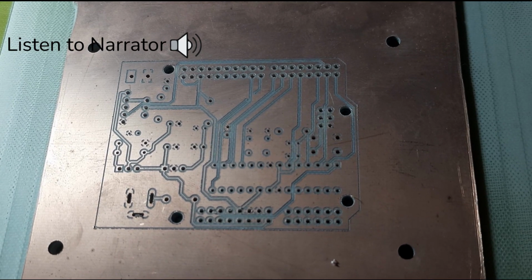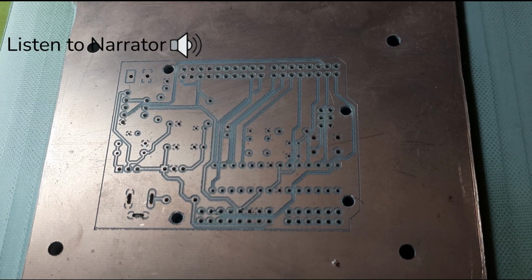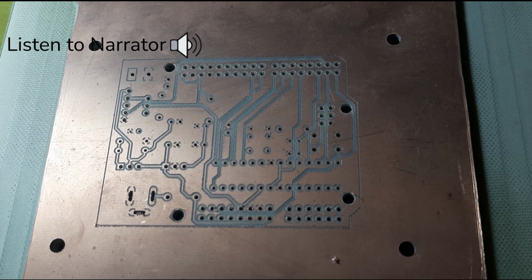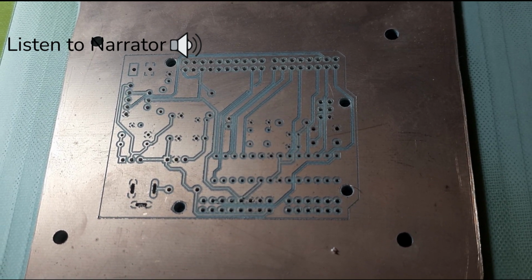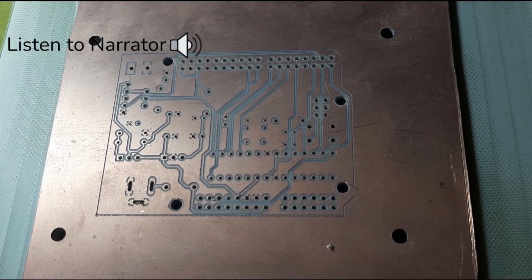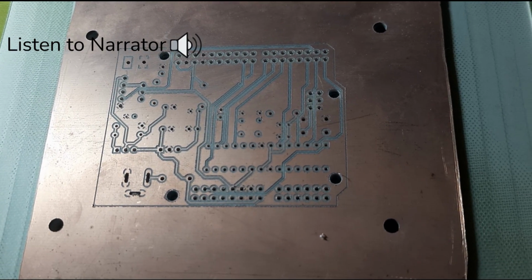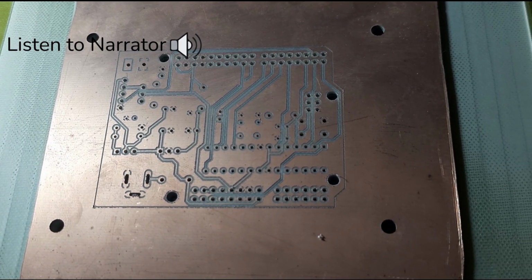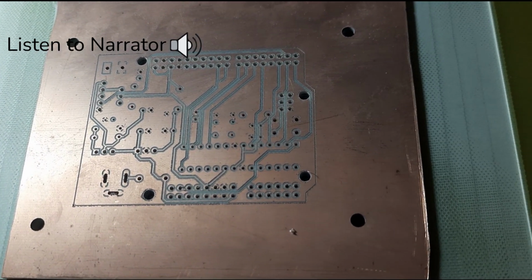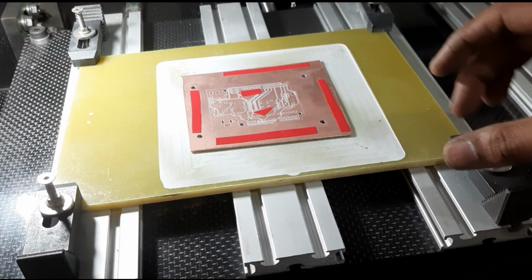All operations on the top surfaces are done. That includes the isolation routing on top, the drilling of different holes using different drill bits, the slots, the through holes non-plated, and finally the alignment holes. Next, we can remove this board and flip it for doing the bottom layer.